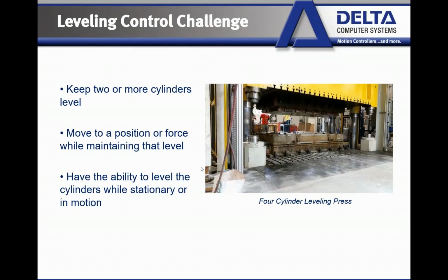So I want the total force, right? If I've got a 4-corner press and one of the corners is sticking way up, either intentionally or unintentionally, I still want to maintain that level. I don't want to tweak my platen way out of shape and try to have the other cylinders press where they shouldn't be. I want the cylinder with nothing under it to be trying to maintain a level rather than just trying to exert a force on a part that isn't there.